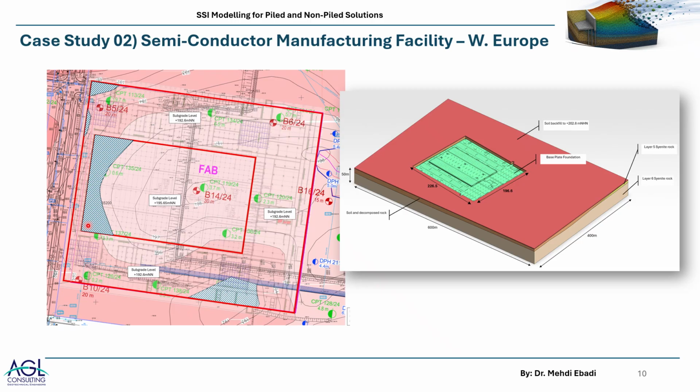This is very important because sometimes you'll see that the layers that you are getting from the model may not fully capture what you are asking for. And that's because the program uses interpolations for obtaining a surface that would get past the bedding plane of each layer in different locations.